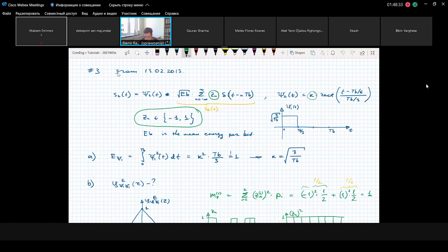In order to find this autocorrelation function, you do it in 2 steps. First, you calculate the autocorrelation function for the basis function itself, and in another step, you calculate the autocorrelation function for the discrete sequence of delta pulses. This is the main flow, and actually you have it for most of the tasks provided. Yes, we have nicer wording there, but in general the idea is that you have something in the middle, autocorrelation or signal or power spectrum density, and then you need to find all the rest of the parameters.